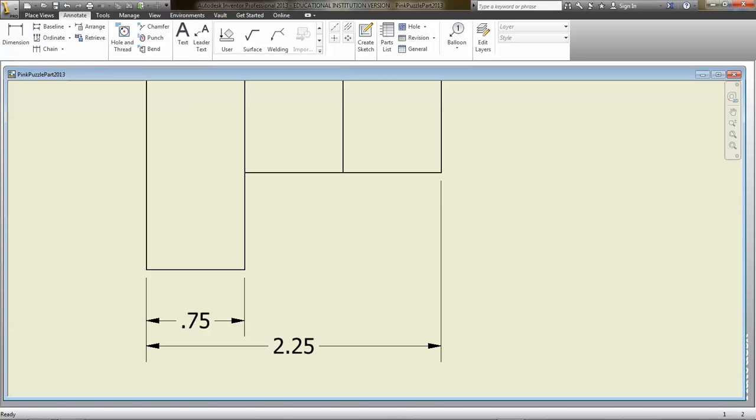If I needed to, say, move the dimension away from center, I could do that. But again, remember, our dimensioning standards say the dimension, the number, the measurement should be in the center unless it overlaps another dimension and it gets confusing. Okay? So there's the basics of creating a drawing file and the basics of dimensioning. And we'll get a lot more into dimensioning further on.